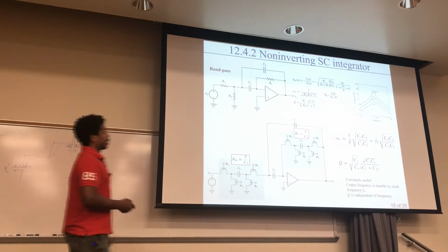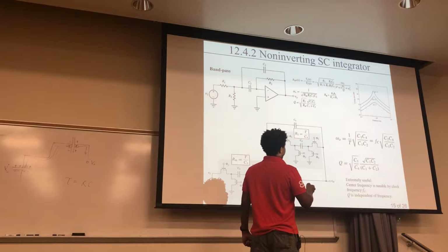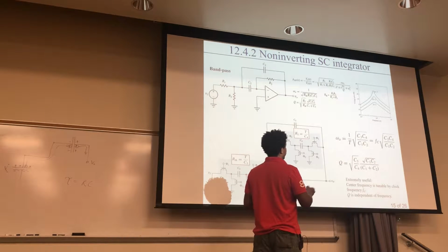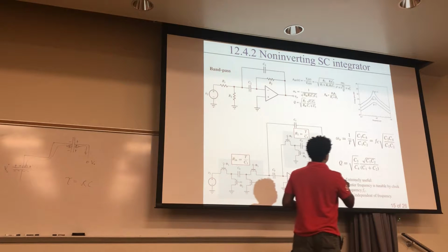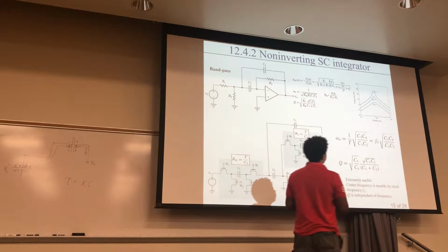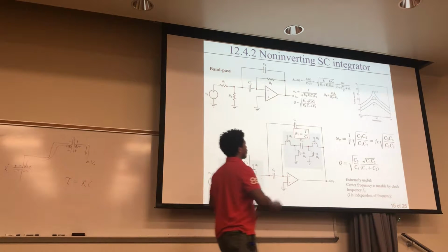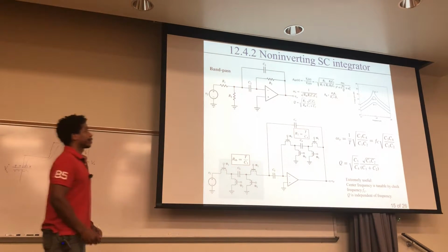So that just means that if you look at this plot right here, for any particular Q you're looking for, let's say you're looking for Q4, the shape of this will remain the same, but the position, this is the cutoff frequency right here, that position can shift. You can have it at a higher frequency or sweep it low, but still hold on to the same shape for Q, for the fall off.